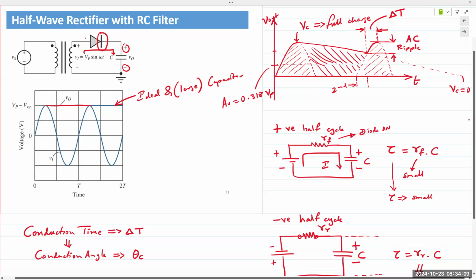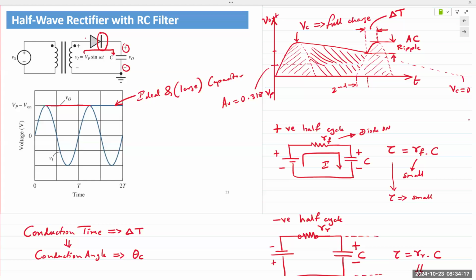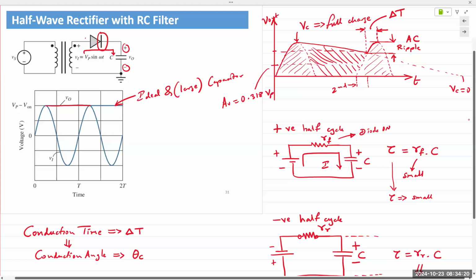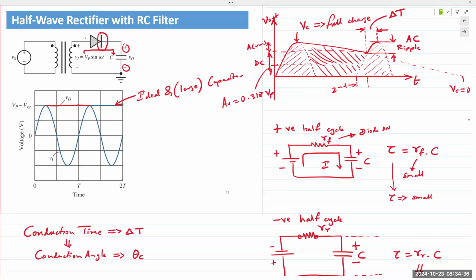Okay, an AC ripple can be measured in both peak to peak as well as RMS. And the actual DC value would be a combination of this DC value plus the AC RMS value of the AC ripple. Now, if you're just using the capacitor, then that ripple typically would be about 100 millivolts or less. So if you have a DC power supply that's about 10, 12 volts, that ripple would be less than 0.01.